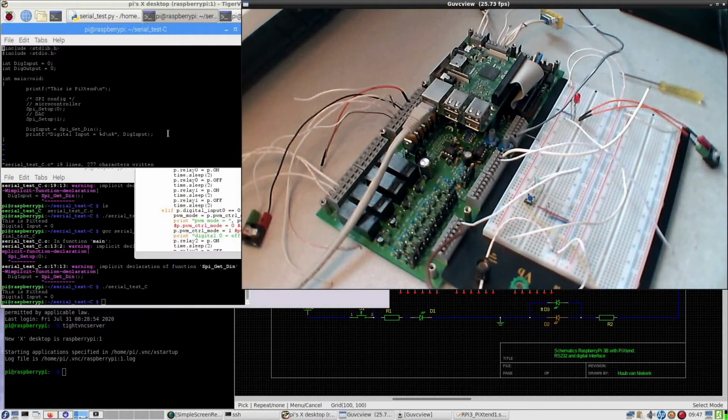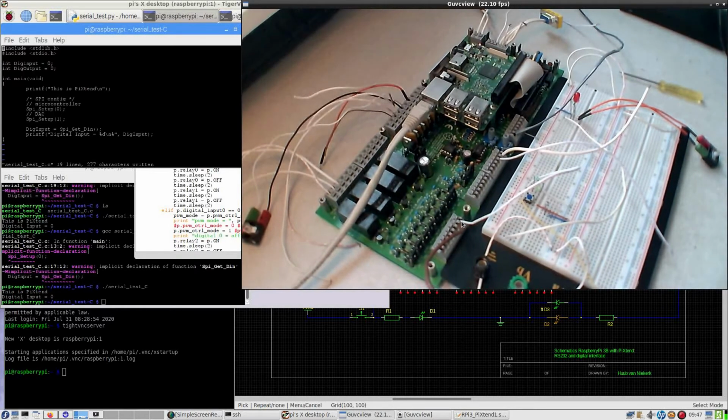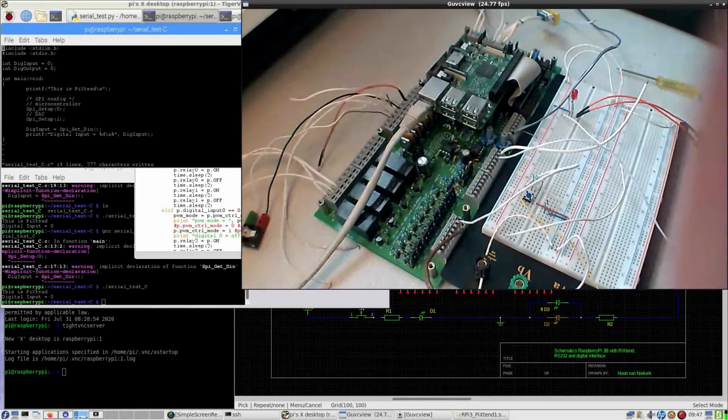Now before I go on, I want to test if the program actually works. Meaning that, of course, I have now digital input, which comes back as 0. So now I have attached the breadboard and applied the 5 volts power that I used to do. I've connected this wire to digital input 0. Now let me refocus a bit. Yeah, better.